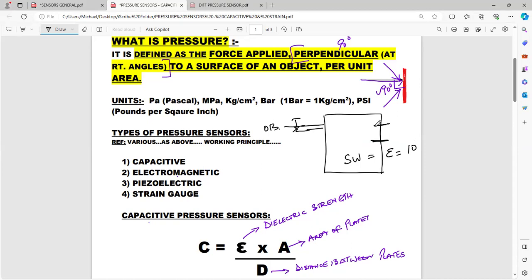This one is also sensing 10. There are two sensors, and what these sensors are going to do is operate certain solenoids and accordingly prevent the oil from going overboard. Depending on what your circuit is on board, they'll either stop the pump or it will have that three-way valve, correct? Yes. Right.